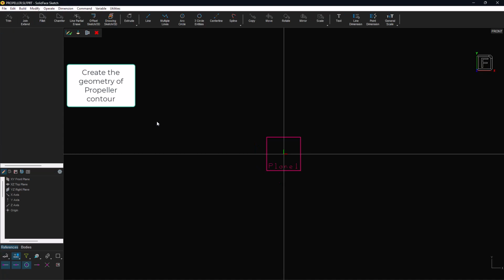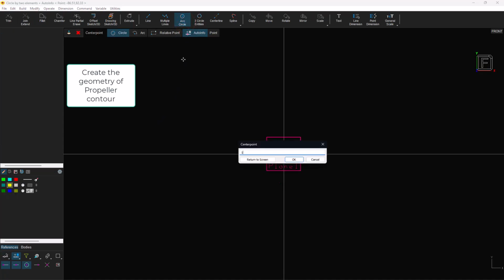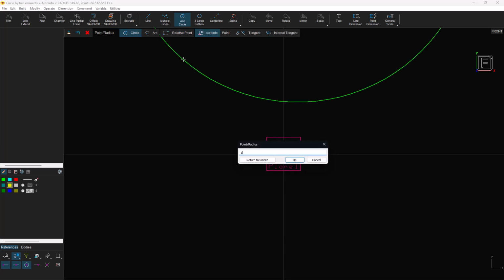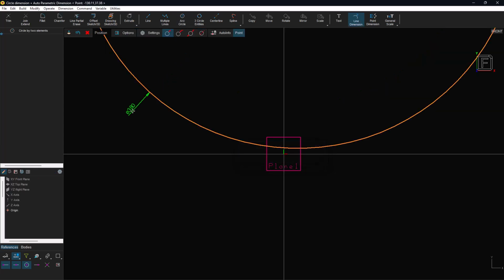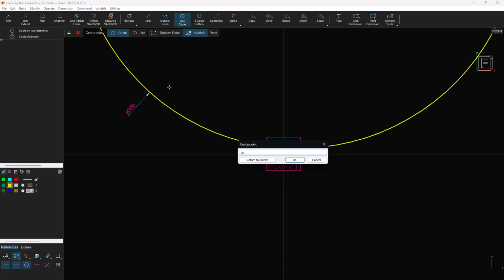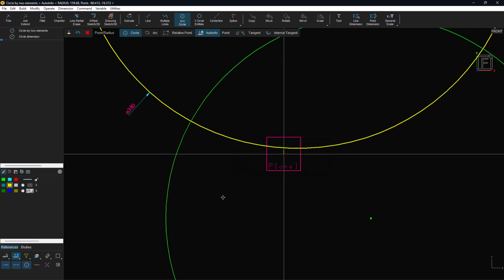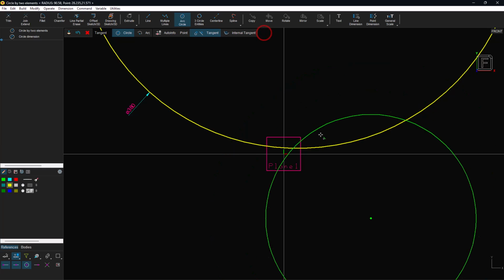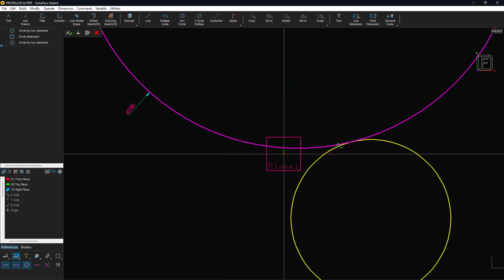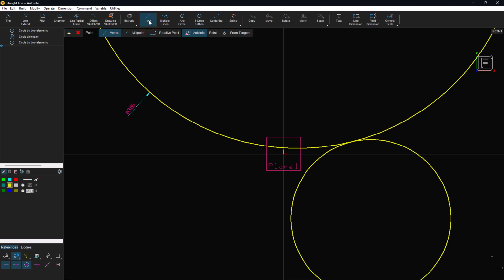Define the sketch. Create a circle, positioned at 12 and 195. Radius of 190. Then a second circle positioned at 75 and -56, and tangent to the first circle. A vertical line at 0 and with a medium distance of 15.